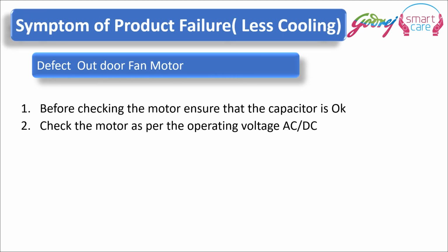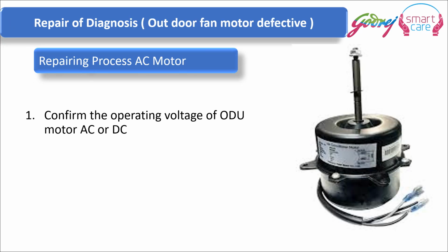In case of outdoor fan motor, before checking the motor, we have to ensure that the capacitor is okay. Check the motor as per the operating voltage, AC or DC. We have to check the operating voltage of the outdoor unit motor, AC or DC.